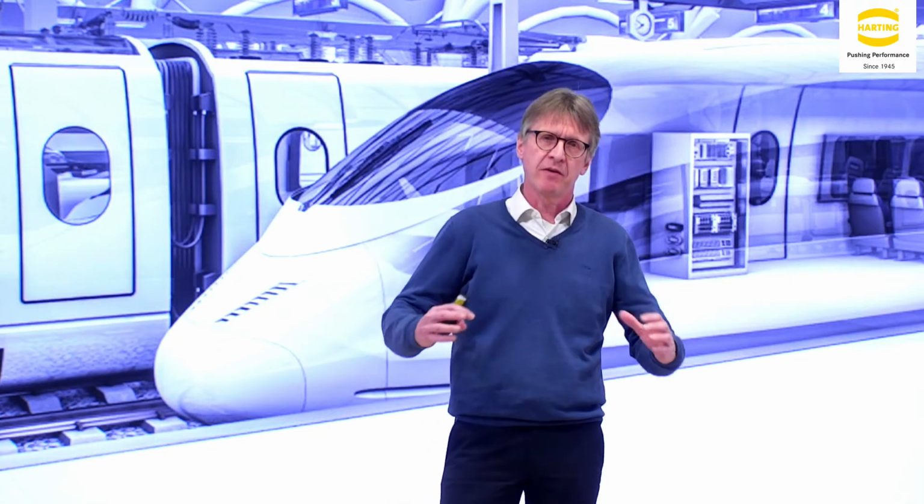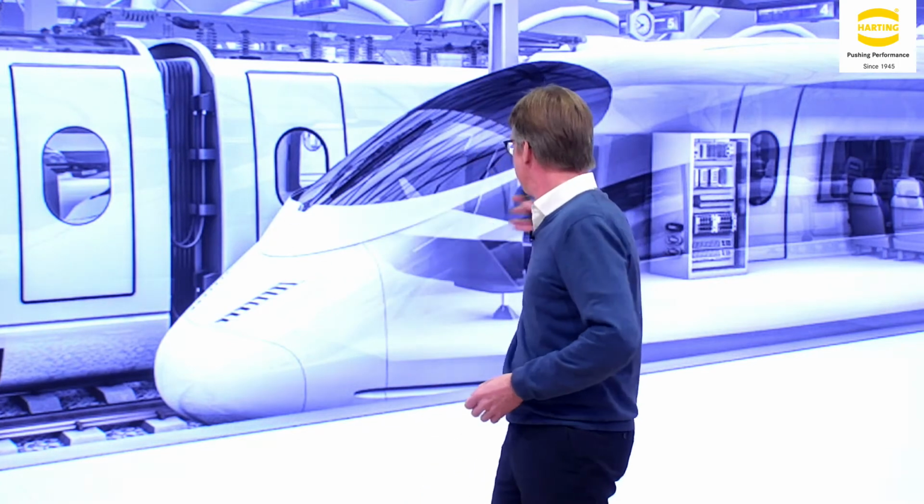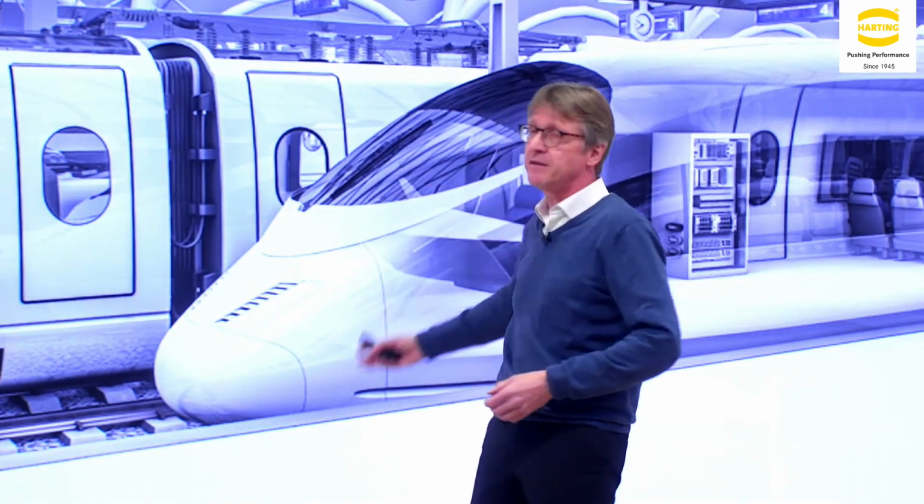So anything you have created in your connector in the past, you don't have to replace; you just replace the one module, in this case for Ethernet. Therefore, the existing hoods and housings can continue to be used unchanged, which is of course a huge advantage in pricing and installation times. These modules for the transmission of Ethernet are used for the backbone installation through the entire train, from the front to the end.